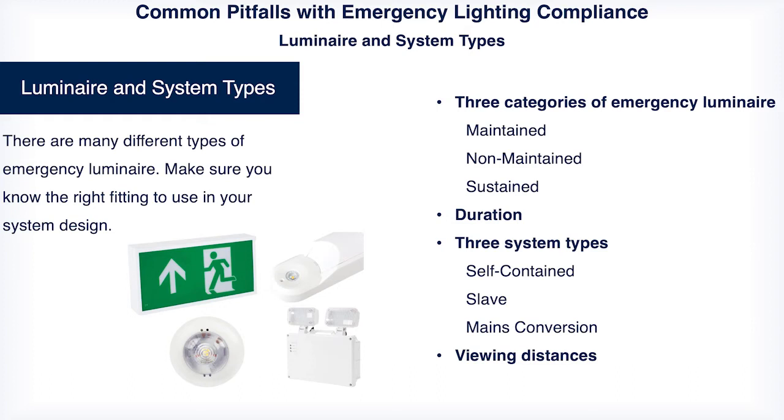Only comes on when there is an emergency and mains failure. A phrase that's still being used, but now much less frequently, was sustained. Sustained emergency lighting products had two separate light sources within the luminaire, one used for mains operation and one used for emergency operation. But with the advent of LED, that requirement has generally been removed. In most cases now, you'll find a single light source in the luminaire that operates under normal mains or under 12-volt battery supply.